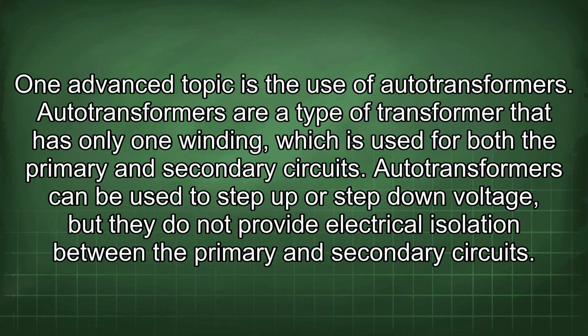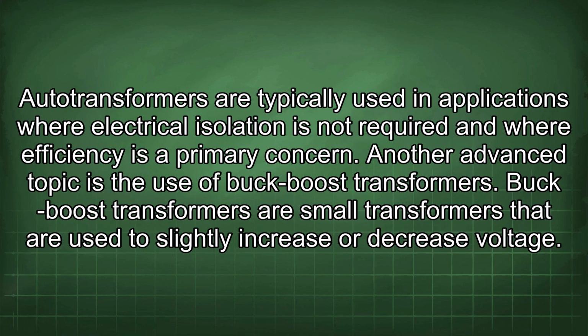Autotransformers are a type of transformer that has only one winding, which is used for both the primary and secondary circuits. Autotransformers can be used to step up or step down voltage, but they do not provide electrical isolation between the primary and secondary circuits. Autotransformers are typically used in applications where electrical isolation is not required and where efficiency is a primary concern.